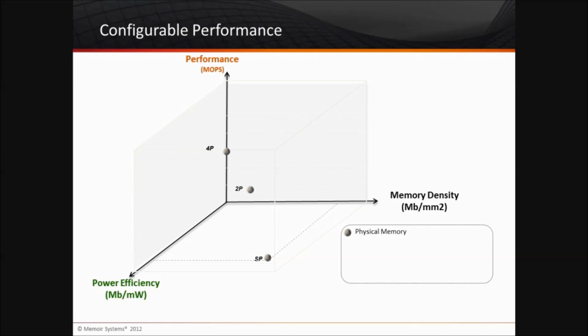In contrast, a 4-port memory, if you built it with circuits alone, you could put 12 transistors together and get 4 axes. It is very bad in density, probably about 1/10 the density of a single port. So it's sitting to the left of the x-axis, but it's very high in performance. It's 4 operations per cycle. So with physical memory alone, you'll see points in this space.